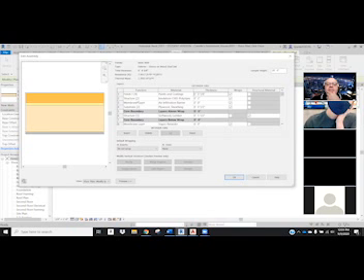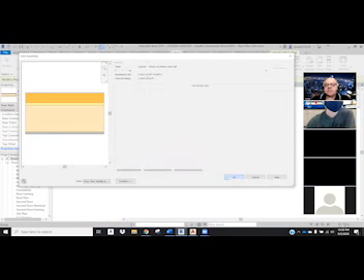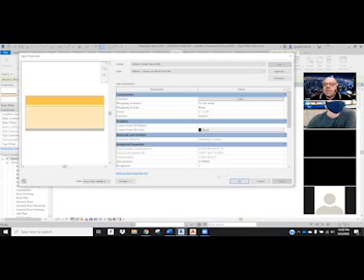Oh, this can't be structure. I've got to change the structure in step 2. Remember I said it had to be a substrate. Structure always has to be between the core, and I got a little distracted. So I have to make this a substrate so that it can be there. And then I can go and hit OK. So if you change that structure to a substrate, then you can save it. Okay, sorry about that. I got distracted with all the emails.